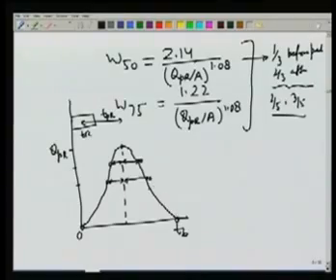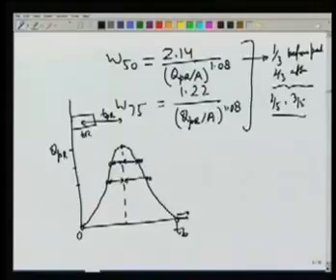The check will be that the area under this curve should be equal to 1 centimeter of rainfall, and if it is not, then we will have to adjust some coordinate, maybe this dB we will have to shift this side or this side. So that little bit of adjustment has to be made in order to maintain the area under the curve equal to 1 centimeter of depth.